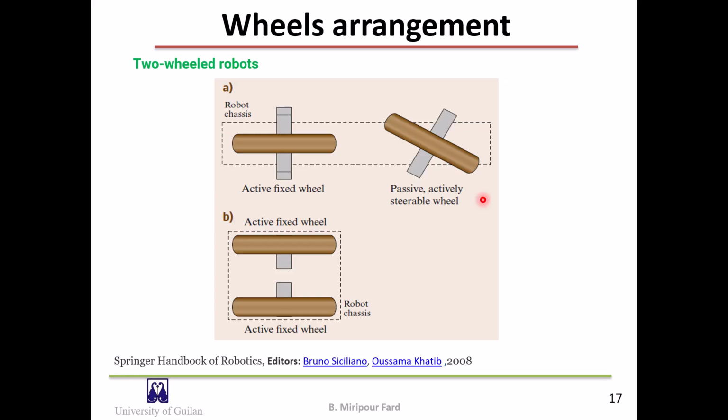Generally, there are two types of two-wheel robots, as shown in this slide. At the top, you can see a bicycle-type robot. It is common to steer a front wheel and to drive a rear wheel. Since the dynamic stability of a bicycle-type robot increases with its speed, a balancing mechanism is not necessarily required.